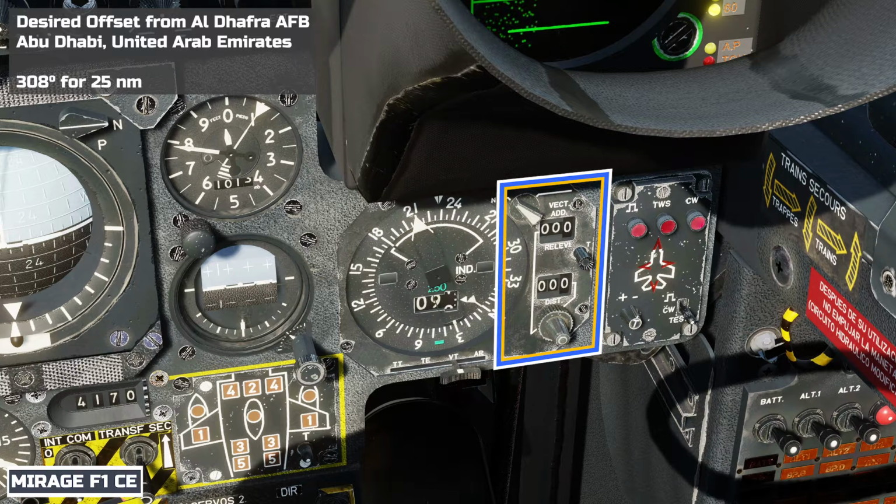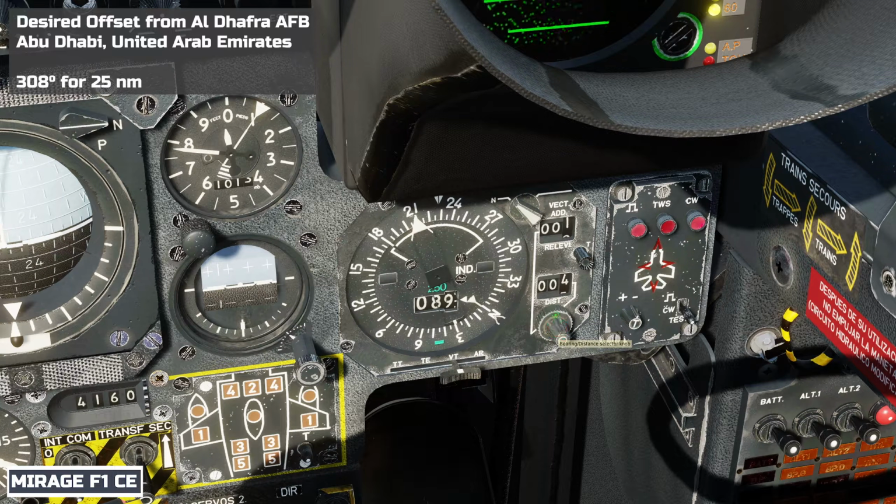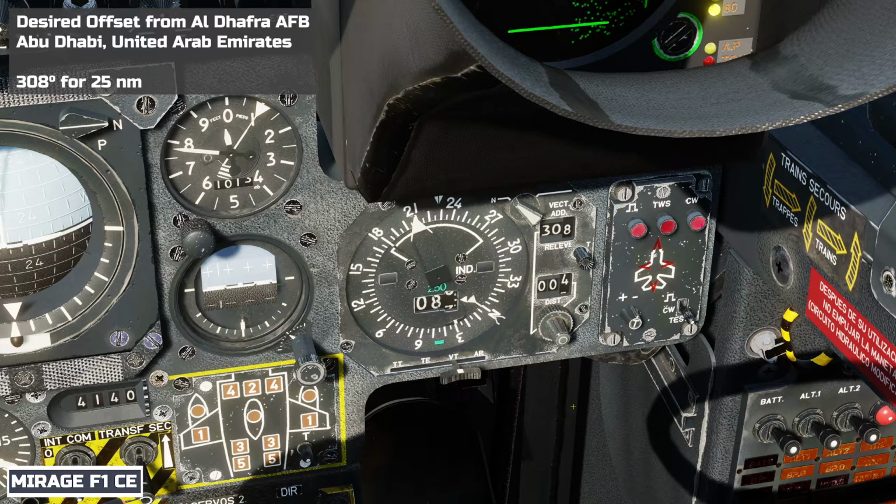An offset is known as a vecteur additionnel in French, as indicated at the top of the controls. The values for the offset are inputted using this knob. First, setting the outer knob to the left, adjust the number in the upper window with the inner knob until it reads the desired relative bearing. Set the outer knob to the right and repeat the process until the offset distance in nautical miles is displayed in the lower window.